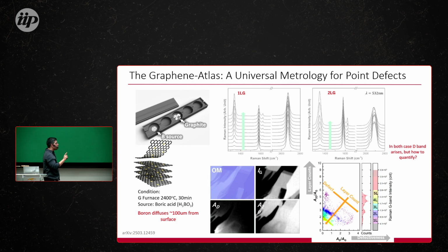There is only one problem when you are working with graphene and want to quantify defects: we only know how to characterize and count defects for one layer, monolayer graphene. That's all. One of the issues, especially if you are thinking about industry, is that we need to quantify. We don't have any model that can quantify defects in different numbers of layers in the system, whether it is graphene or any kind of TMD material. We do not have that. We just know how to count defects for monolayers.